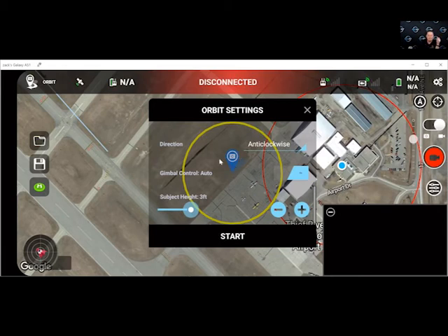So when we put this out there on the map, it could be that the top of the tower is not centered in your frame, or the bottom of the tower, whichever it is that you're looking for. Being able to have manual control of that gimbal allows you to make those little adjustments on the fly to really keep whatever you want to look at in the front of your screen. Typically I use it on tall structures, because that's where I run into the problem.